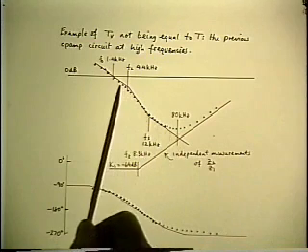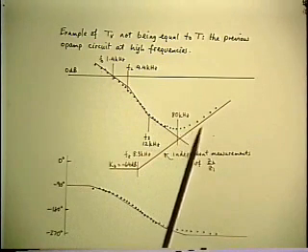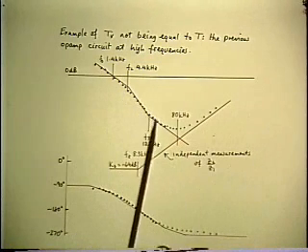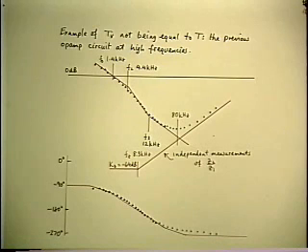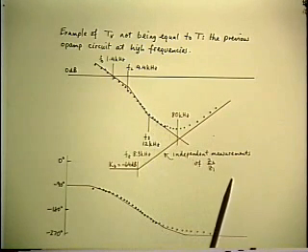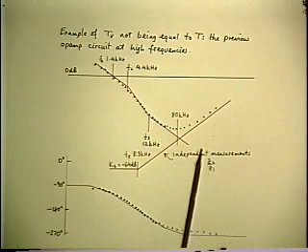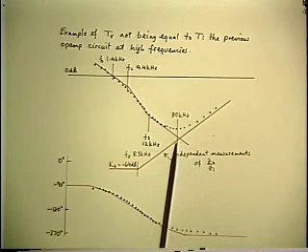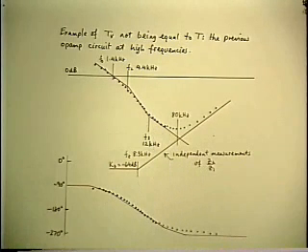Because what I'm measuring is really the sum of T and the impedance ratio, and because it's the sum of two functions, whichever one is the bigger one is going to dominate. And that looks as though that's what happened. In other words, the true value of T became so small that even though the impedance ratio was small, it wasn't small enough, because one of the inequalities is Z2 over Z1 has to be much less than T, and it wasn't. So it looks as though that's the right answer.